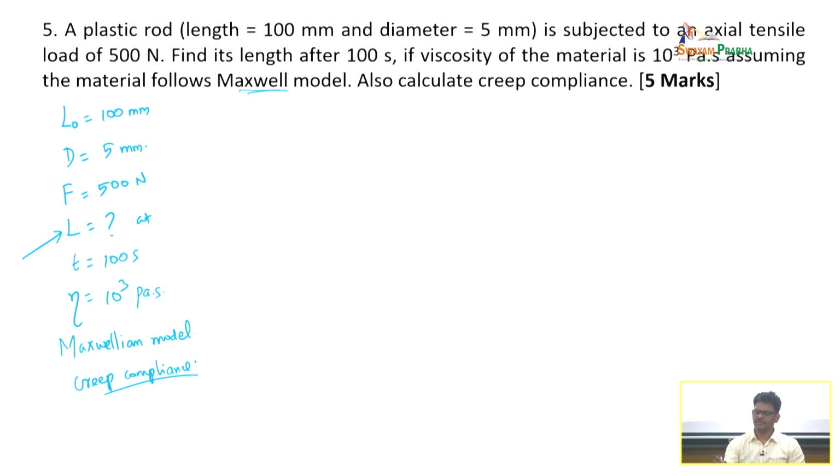The fact that I am asking for creep compliance means it is a creep test. That means you apply a load for a long time, and you look at how the elongation strain develops as a function of time. So, this is a creep response. Another possibility would be stress relaxation, where you give a constant strain and look at how stress develops. So, the first thing you have to decide is whether it is a stress relaxation or a creep response. It is a creep response, obviously.